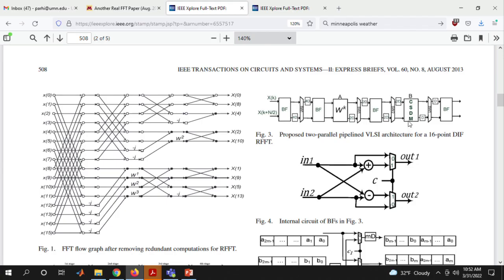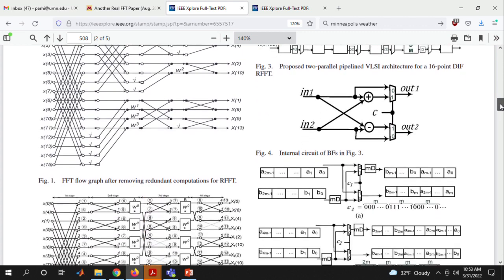Then those coefficients are going to be 1 by square root of 2 plus or minus j 1 by square root of 2, and that 1 by square root of 2, which is 0.707, could be approximated by a few non-zero bits, so-called canonic sign digit, and that's why those multipliers could be implemented by a so-called canonic sign digit multiplier. Yeah, I didn't talk a lot about arithmetic, which, as I suggested, you can watch on YouTube, where we talk about canonic sign digit representations.